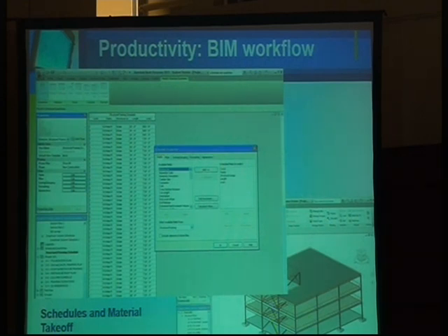In this one here, I'm trying to figure out how many beams, all the structural framing elements. So I'm trying to run a schedule by counting the number of beams used in the entire project. And then I can group this by floor, okay? Or I can group them by size. So you have so many ways. And then I think we'll do some of those in